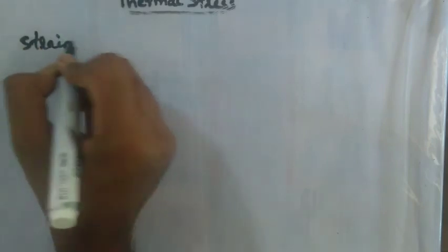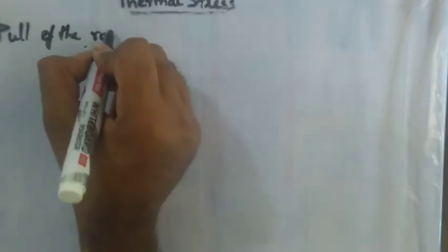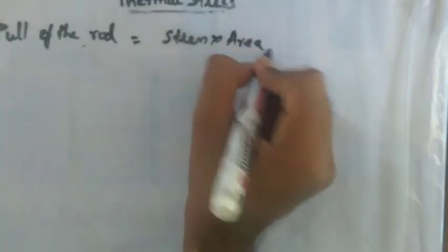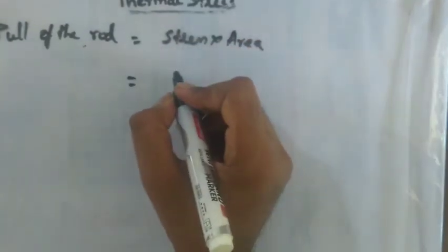We got one answer. The question did not ask for strain, they asked for the pull of the rod. Pull of the rod is equal to stress into area.